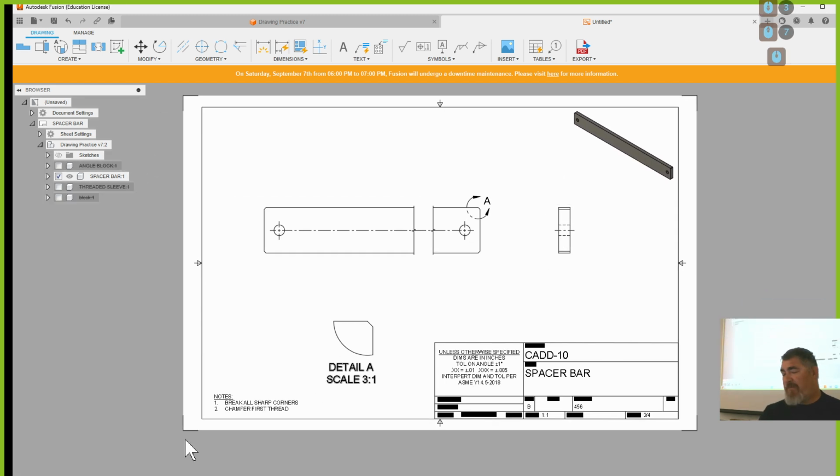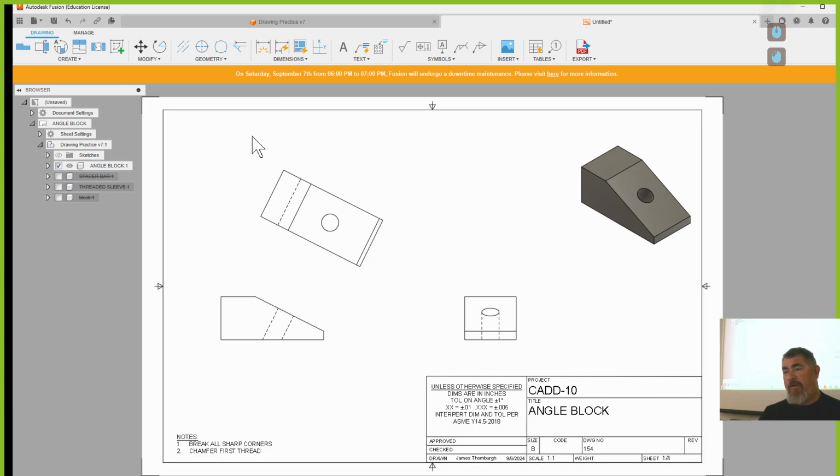So now I can have that center mark there. If I go here and I use the center mark and put it on here, look at that. Now I'm making a line to that view. So that helps make the straight line that we need. So later on when we get to dimensioning it, that's going to make it easier, because we can dimension to the center marks. Okay, any questions on any of that?